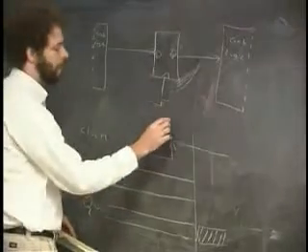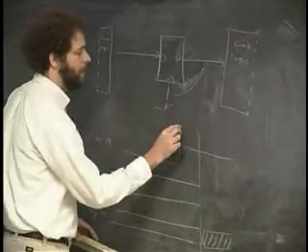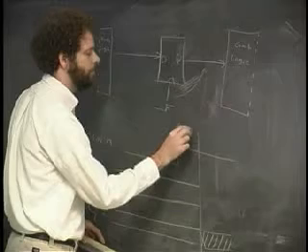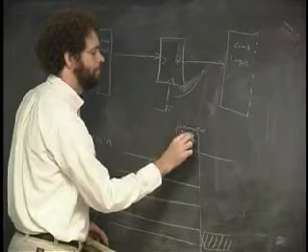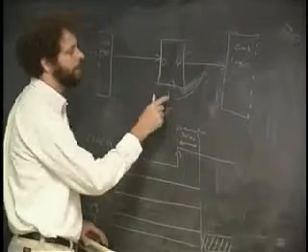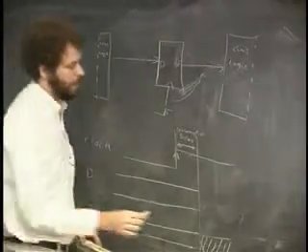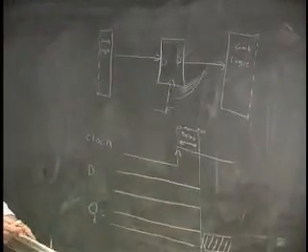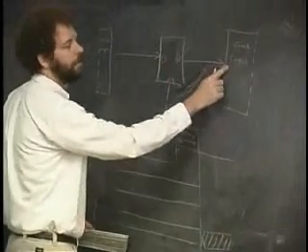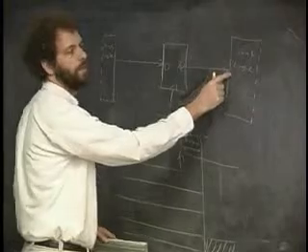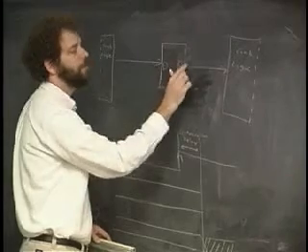And this time between when the clock goes from low to high and when Q starts to change is called the contamination delay. This time here. How long does it take to contaminate the signal between when the clock goes off and the signal gets messed up? Is that the length of the arrow on the right side? The arrow that I'm making here, or do you mean this arrow? No. It has nothing to do with how long this wire is, okay? What it is inside of this box, there is a process which takes place. I'm assuming the wire is very short.